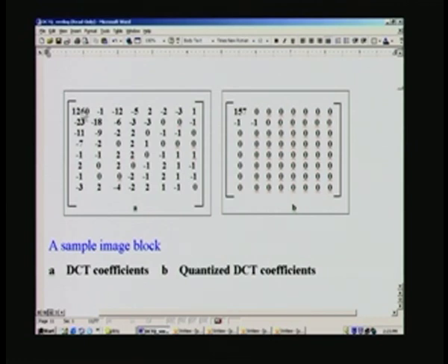For each of these corresponding elements, it may be anything from 0 to 255, being 8 bit for the actual pixel values, and you will normally be seeing some 156, 160 like that, all around that. It may be on an average as far as the input pixels are concerned, and DCT is nothing other than evaluation of 3 matrices C, X and CT, and the final result will be an 8 by 8 matrix, which is what is shown here.